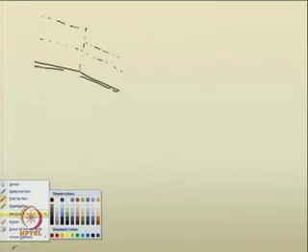Say this, in this case the milder channel followed by a mild channel having both the critical depth same, normal depths like this. There may be a chance of flow profile connecting like this.